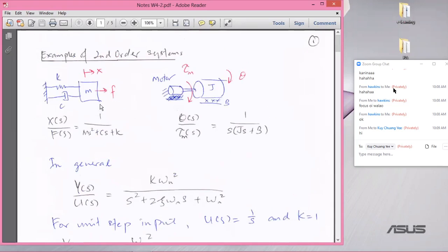Okay, let's go here. So sometimes you're going to have oscillation. Sometimes, depending on the ratio of K, C, and M, you don't have oscillation. For example, when the damping is large, there is no oscillation. The mass is just going to stop. But if the damping is so small, and of course when you apply a force here, sometimes a step force or whatever, sometimes it's going to oscillate and then it's going to stop at its final value.